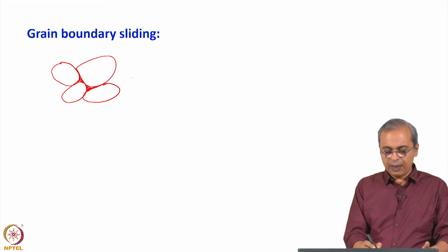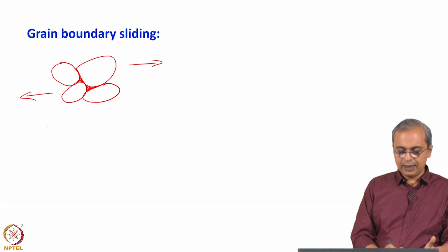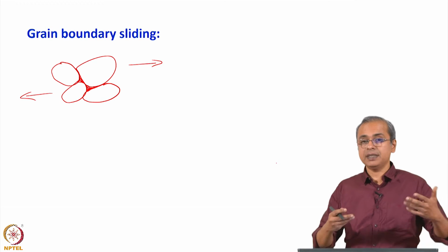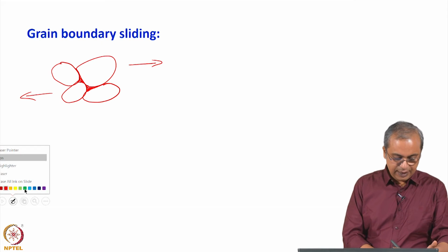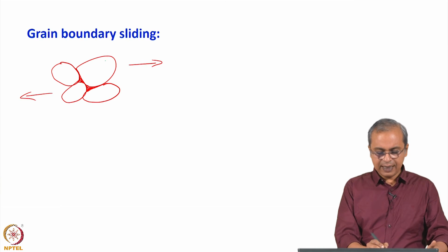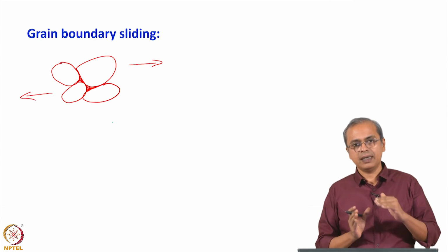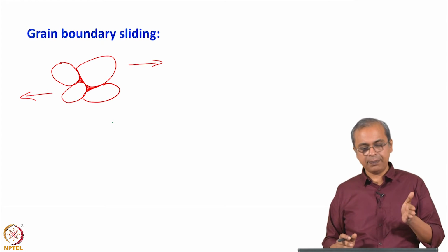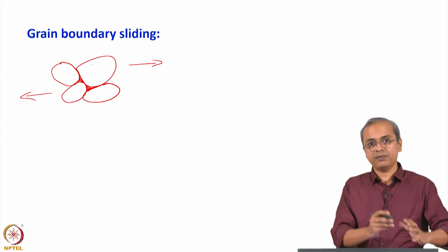So now when you apply a stress, and let us say this is how this set of 4 grains is perceiving the stress in the context of this testing, then a lot of things are happening. As you pull, normally we are talking of plastic deformation occurring because you have dislocations moving through the individual grains, and so the shape of the grain itself changes.